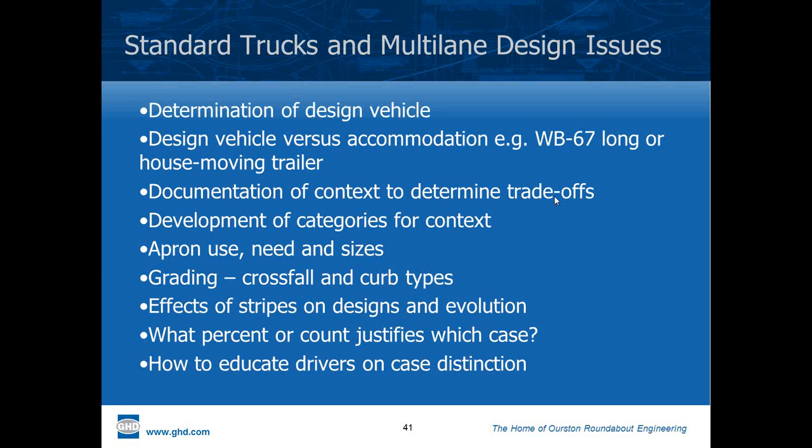It's important, though, as we talk about design trade-offs, that we have a thorough discussion of this, between agencies and designers, whether it's consultant or in-house staff, and that we document those discussion points and trade-offs, because a roundabout that's very accommodating of trucks is not necessarily going to be the safest roundabout for pedestrians. And I'll show you some designs.